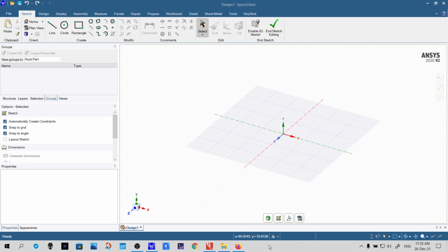One of our viewers requested a video on the process of importing an ICEM CFD file, or simply the geometry file that has already been prepared in ICEM CFD, into SpaceClaim so the meshing process can be accelerated. For Fluent Mesher it is easy to import SpaceClaim files, and the geometry properties don't get distorted.